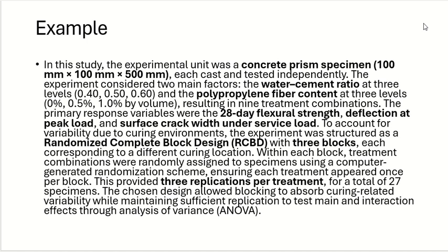Or when the water cement ratio is very high, what am I supposed to get? Lower strength or higher strength? It depends. But if I just focus on it being too high, it's low strength, right? Okay. So it will start to impact these logical findings, because you ignored something which has an effect. So the point is you have to acknowledge the source of variation in the data and consider it in the design even if you have practical limitations.